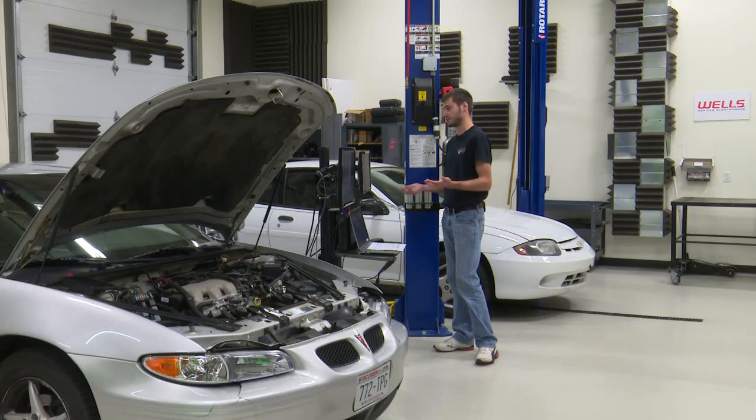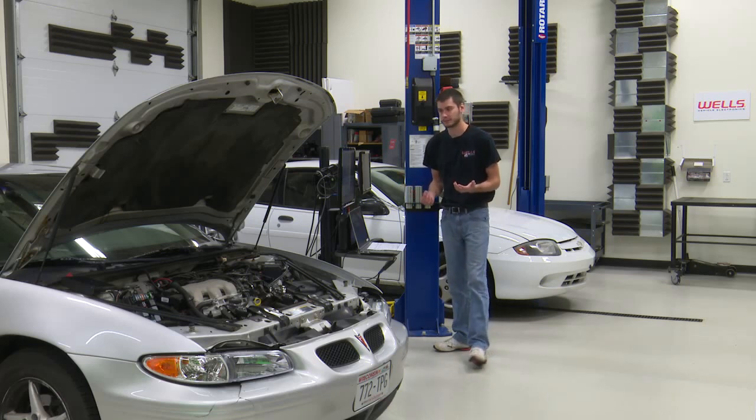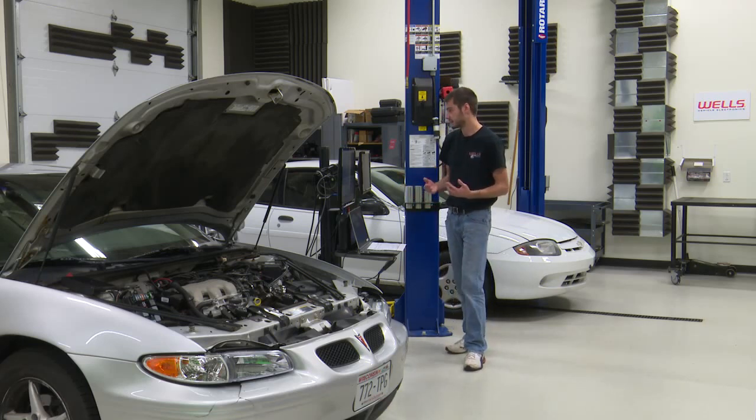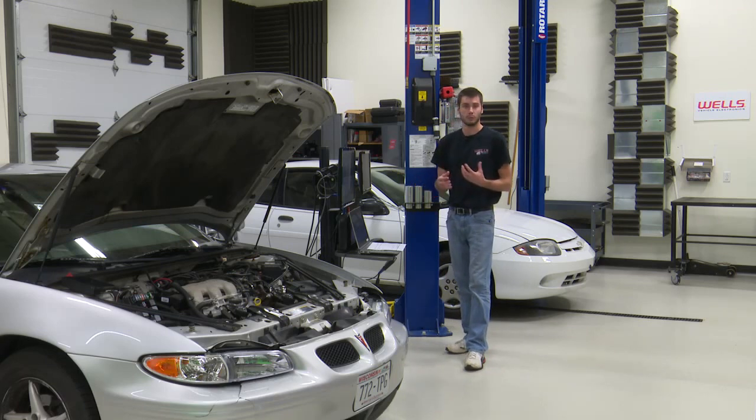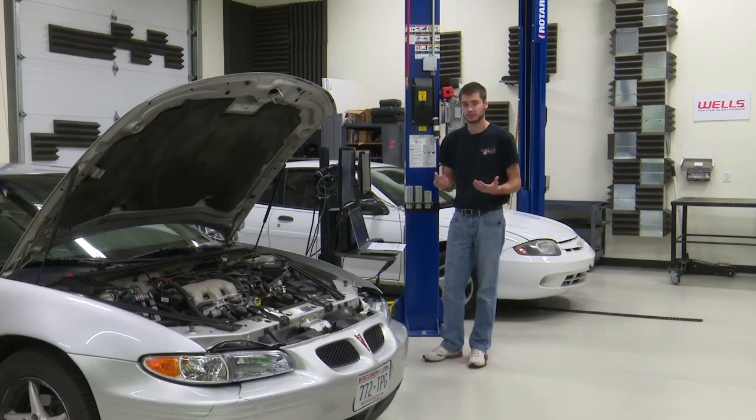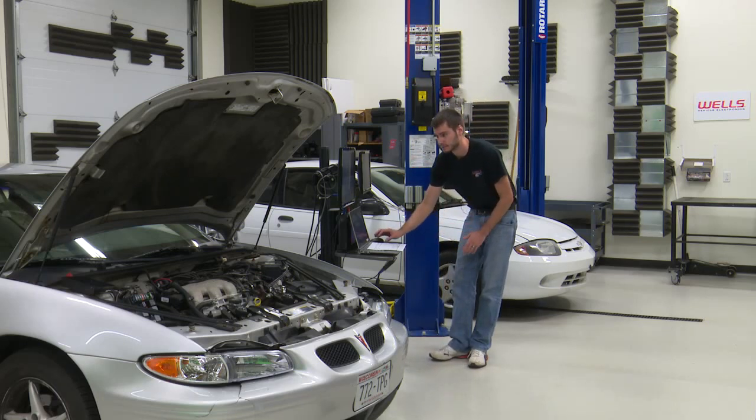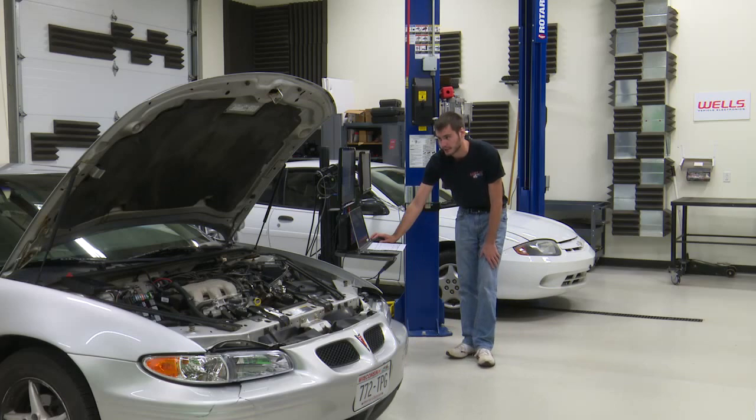That's correct. It's not fast enough. You hook a scope to it, and it's going to be instant. You're going to see exactly as fast as you can do it. It's cycling and watching multiple times more per second. Scan tool's only able to get so many times per second to sample. So we can speed this up a little bit by changing a few things.